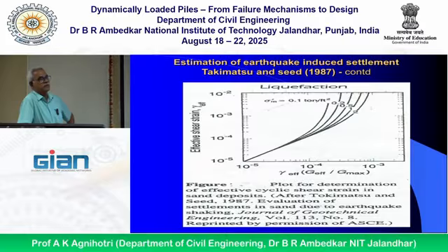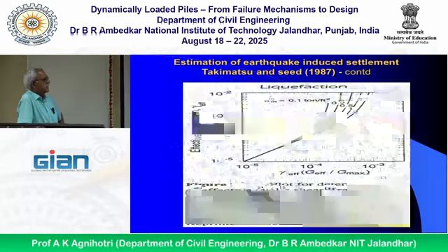So directly from the definition you will not be able to get the effective shear strain. First we have calculated gamma effective times G effective on G max. Then whatever sigma m dash value you have, you will select that curve. Corresponding to that you can calculate this gamma effective strain.